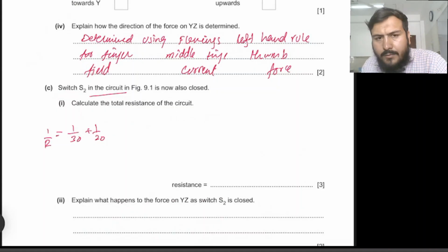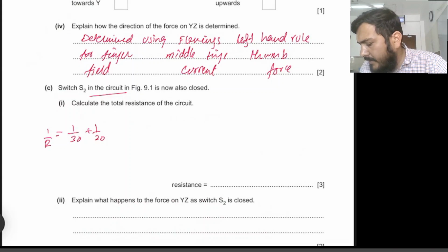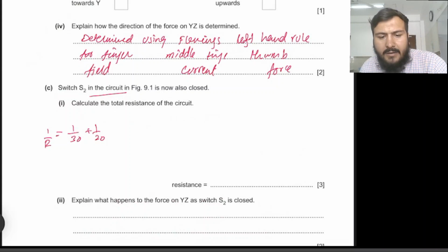Alright, so you need to calculate these resistances. These two are in parallel and this other one is in series with them. So you need to calculate 30 and 20 in parallel and then add 28 to that, and when you do that you would eventually get your answer as 40 ohms, right? Okay, next,